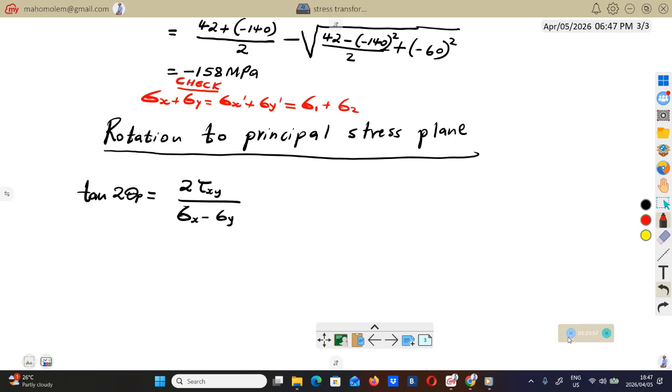Yeah, the stresses must always balance. The normal stresses before you rotate the element, the normal stresses after rotating the element, and the principal stresses: the sum of those stresses should be equal. That is due to the fact that when one increases, the other decreases. When the normal stress on the X face increases, the normal stress on the Y face decreases, and so forth.